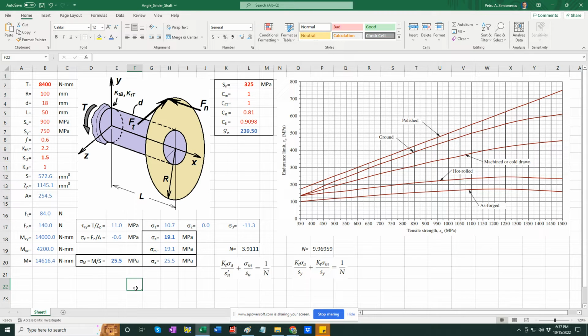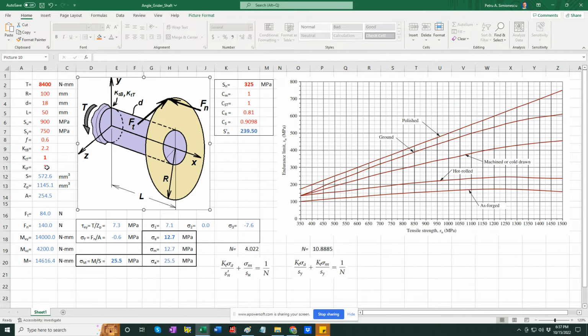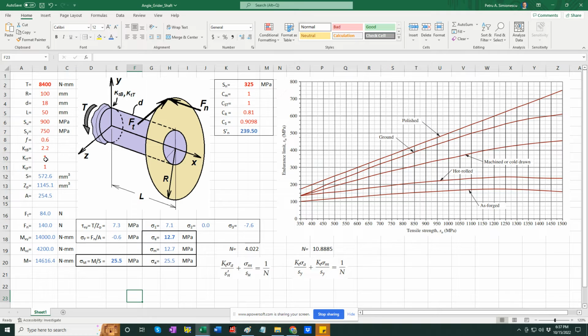Okay, and here I have the stress concentration factor included. I'm making it 1. A fully specified problem should include, or you should extract, given information about the step and the fillet radius, the compressive or tensile stress concentration factor. So I made this 1 just for these calculations. And what do we see? The two stresses, one is sigma x, the other one is tau xy.